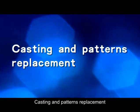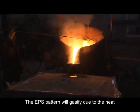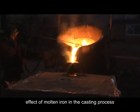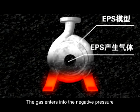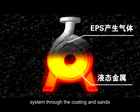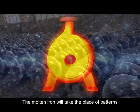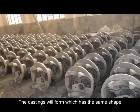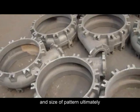Casting and pattern replacement. The EPS pattern will gasify due to the heat effect of molten iron in the casting process. The gas enters into the negative pressure system through the coating and sands. The molten iron will take the place of patterns. The castings will form, which have the same shape and size as the pattern ultimately.